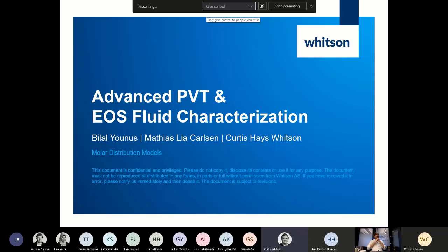And with pretty much any of these software programs, the default characterization should get you ballpark predictions, with the exception of these more complex near critical phase behaviors, from the get-go. And if it doesn't, it's kind of a red flag. About the only reason that it wouldn't do it is that you've got the wrong starting gravity molecular weight relationship that's saying it's too paraffinic or too aromatic.